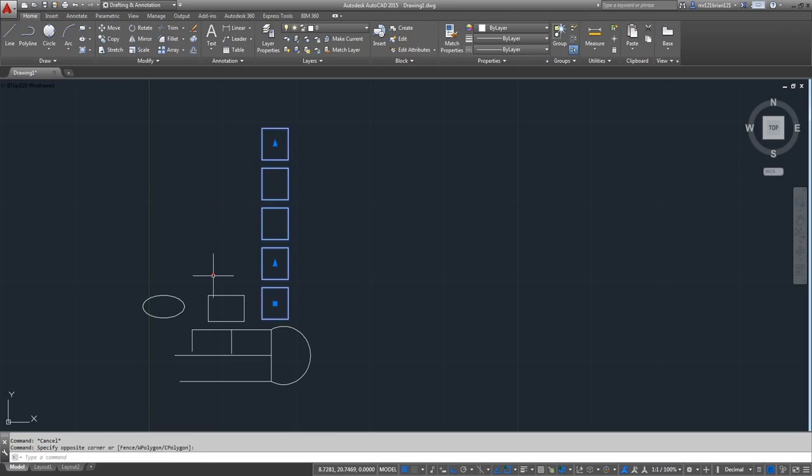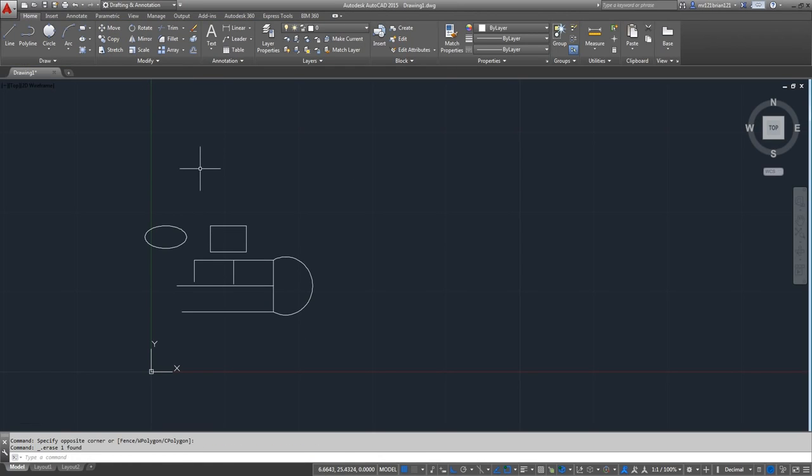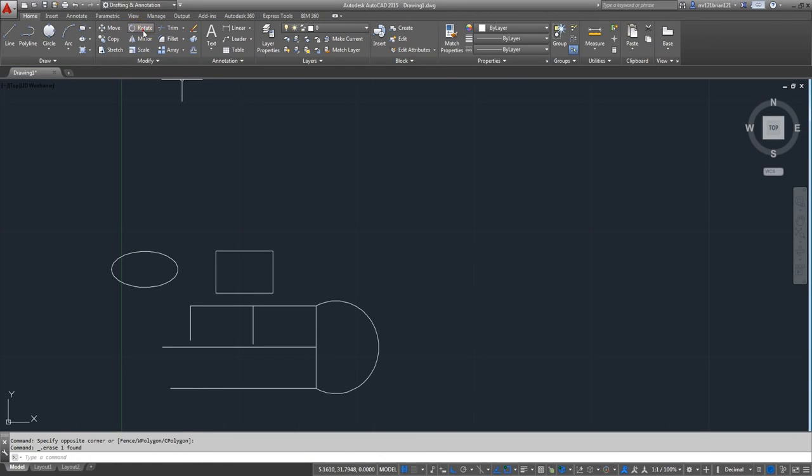Okay, let's go to another command. Rotate. For example, I have this rectangle, we select it, we press enter, we select where we want to rotate it from. For example, the endpoint, this one, you can rotate it something like this, or you can also, if you press F8 or touch here, you can rotate at any different angles you want. Click, and that's it.